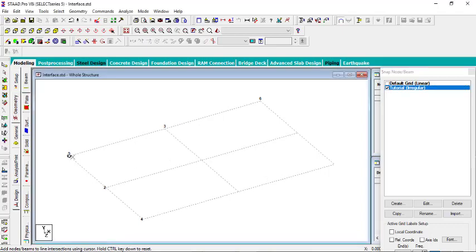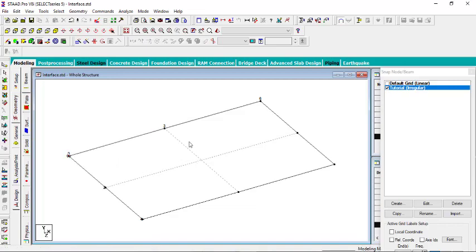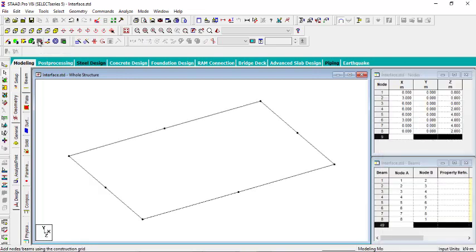So what we just did is create an axis. So let's connect all of this with beam. You just click on this point and drag to this point, also drag to this point. Something very simple like this. You don't need to click anything. Okay, and then you can click on escape, then click on this snap mode, click on it again.